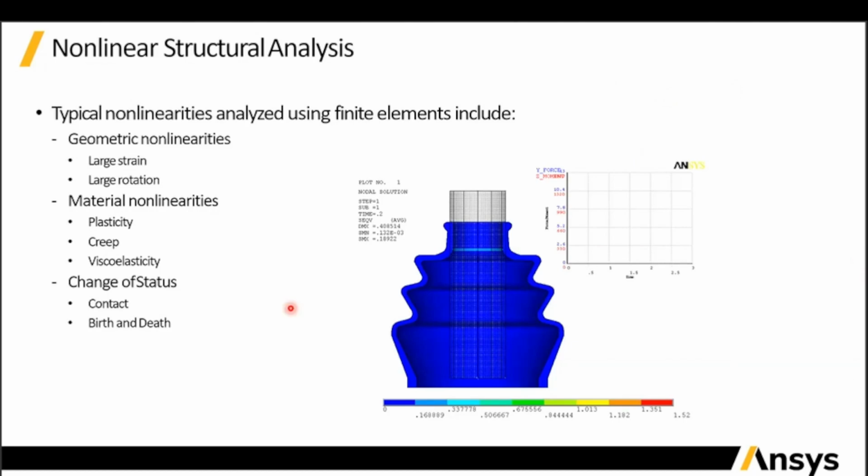Then another cause of material nonlinearity may be creep, or viscoelastic material. Also, there are different types of nonlinear materials, like hyperelastic materials, rubber-like materials, and so on. Whatever the nonlinear behavior of your material curve, it is called material nonlinearity whenever you are doing a structural analysis.